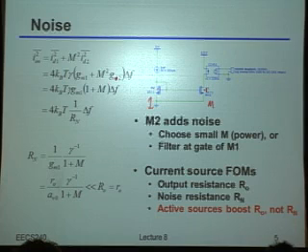That's kind of bad news, right? That basically says that if I really want to mirror things up like this, then I could be picking up a lot of extra noise if I'm not careful about it. Now, the good news is there's actually a couple of things you can do to fix this, both of which are hinted at on the slide here. So what's the first, really brute force way of trying to make sure that you don't pick up too much extra noise by doing that current mirroring?